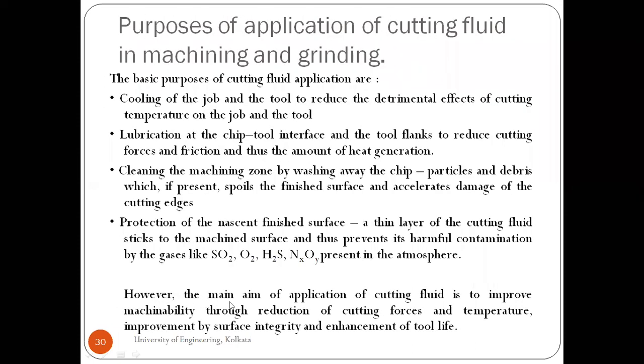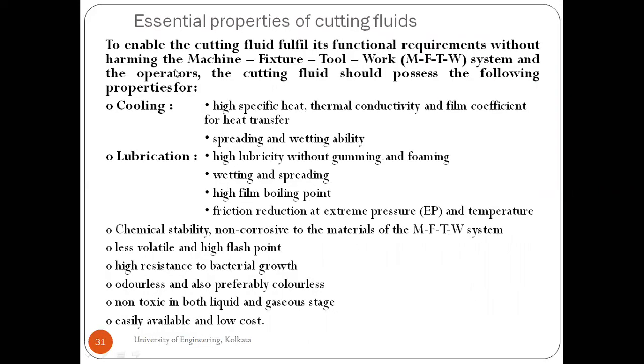Now, the main aim of application of the cutting fluid is to improve the machinability through reduction of cutting forces and temperature, improvement of surface integrity, and enhancement of tool life. The essential properties of cutting fluid are cooling properties, or a high specific heat is required. Thermal conductivity of the cutting fluid is very important, and the film coefficient of heat transfer is also very important. Next is spreading and wetting ability. These things are very important for the cooling aspects.